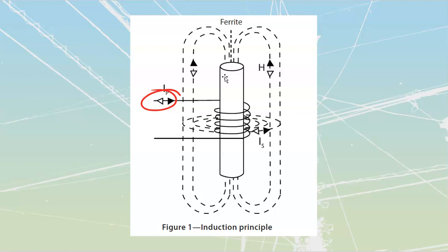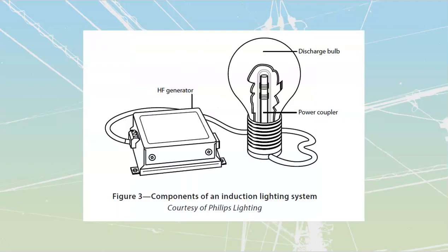As far as efficacy goes, they're pretty good light, relatively good turnover from my watts into my lumens, 65 to 70. They do have a ridiculously long lifespan of the actual tube. Because if you take a look at the tube, there is no cathode to burn out. We have no amalgam that we're trying to have. It's already just pre-distributed gases inside there. And if that tube never develops any sort of a crack, you're going to be fine. Those gases can't get out. So the bulbs themselves have a ridiculously long lifespan that is rated for 100,000 hours or more. Okay, we're just going to write that down there.